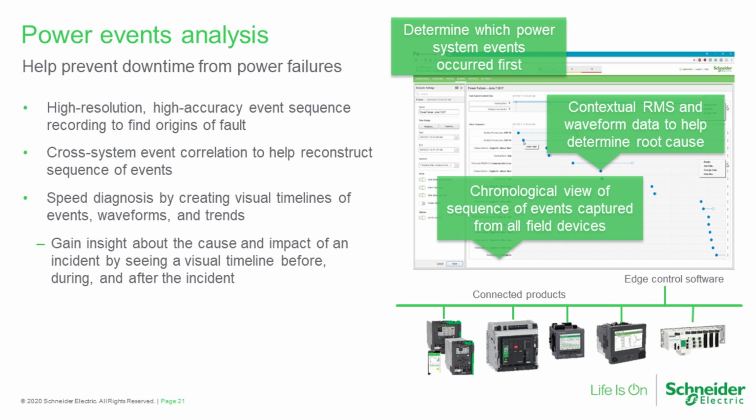Did the transfer switch and the load management system operate the way they should have? Maybe you had a stuck breaker, or you had a wrong priority on a load restoration scheme. You will not find that, as an operator, unless you have good analysis tools to do this.